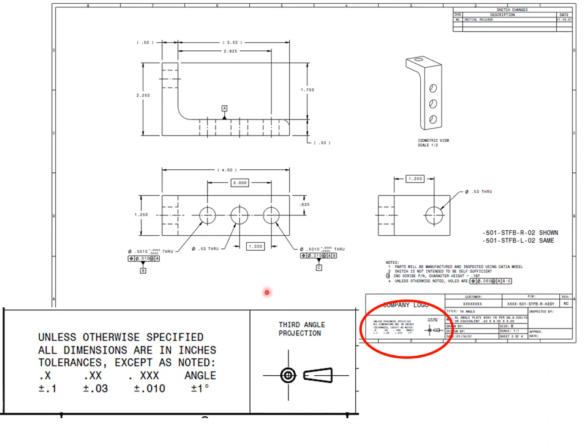Okay, another thing you see in a drawing are tolerances. So inside the title block, you'll see what tolerance you are using. The machinist, first thing they'll look at is, okay, they see the dimensions, but are these inches? Are these millimeters? A quick way to find out is just look at the title block. Unless otherwise specified, all dimensions are in inches.